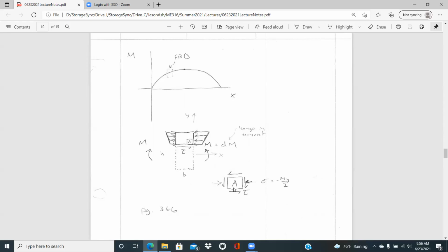But when you look at chapter 7 in your textbook, what this transverse shear stress leads to, say in wooden members, is a shear stress at the neutral axis that can lead to a crack running the length of, say, a rectangular beam located at the center of the beam. And that's due to the transverse shear stress component as that's trying to bend and developing those transverse shear stresses.